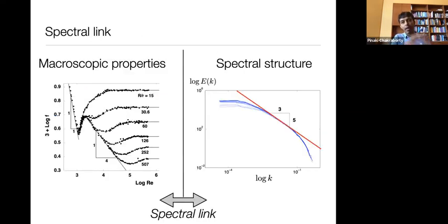that we have been working on. The motivation for this kind of approach is to think of it in the following way. If you pick a standard textbook on turbulent flows, you would find some chapters devoted to macroscopic properties like friction, and here's the Moody diagram. And disjoint, separate chapters are devoted to spectral properties like the energy spectrum of the field. What we are basically saying is that these two are in fact intimately tied to each other. They're linked, and that link, in the simple model I've described, is what we are calling the spectral link. If you know the spectrum, we can predict how the friction is going to behave. And from a conceptual point of view, we know a lot more about the spectrum than we know about the friction. That is the motivation to pursue an approach like this.